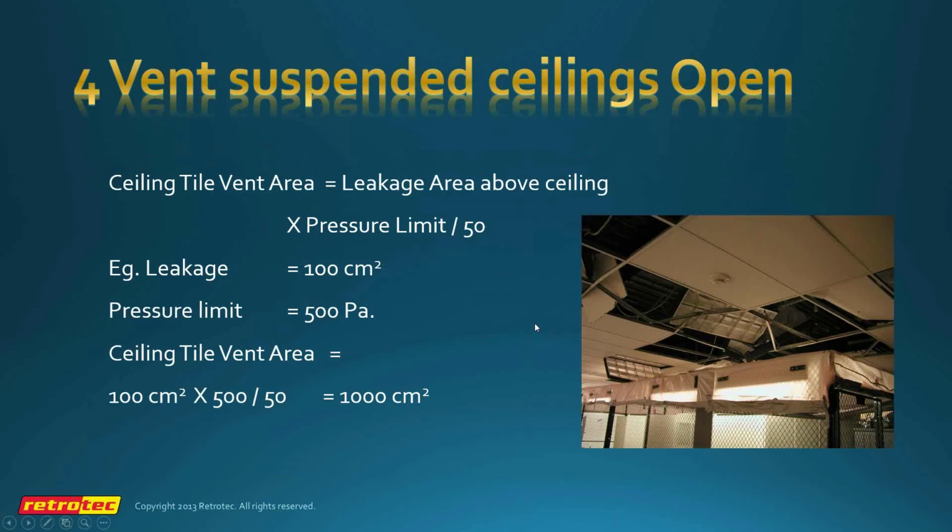So here's the point that I was making about venting the suspended ceilings. This particular problem may have been caused by venting going from the enclosure up to the suspended ceiling, up through the suspended ceiling to holes above it. It could also be caused by the velocity of the agent hitting the tiles. Looks to me like this particular one is caused by there not being any honeycomb tiles in the suspended ceiling. So they kind of learned that lesson.